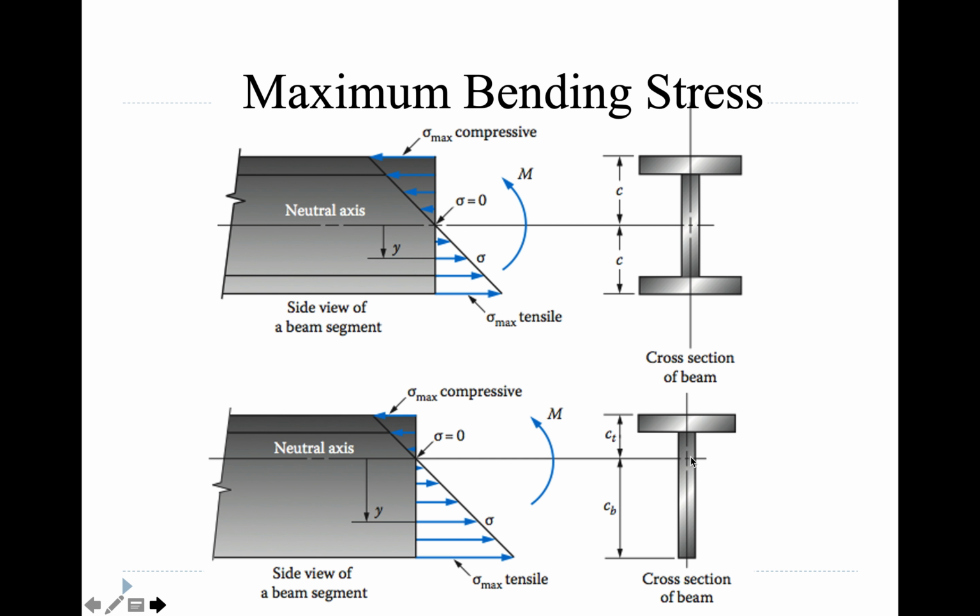Well, a T-shaped beam like this is not symmetrical, right? There's not this piece down here anymore. So the neutral axis moves up, and the neutral axis is where? At the centroid. So again, if you hated that lecture, here it comes again. The centroid is also where there's no force. Designers will use this principle to their advantage and maybe put some conduit or lines there, or do something with it. But that's where stress is 0.